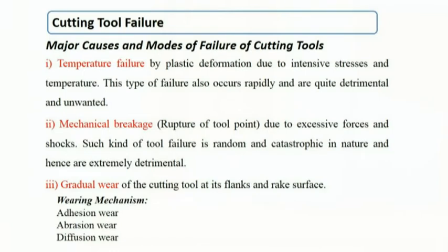The third mode of wear is diffusion wear. So sometimes at high temperature the atoms have a tendency to move from a higher concentration area to a lower concentration region.